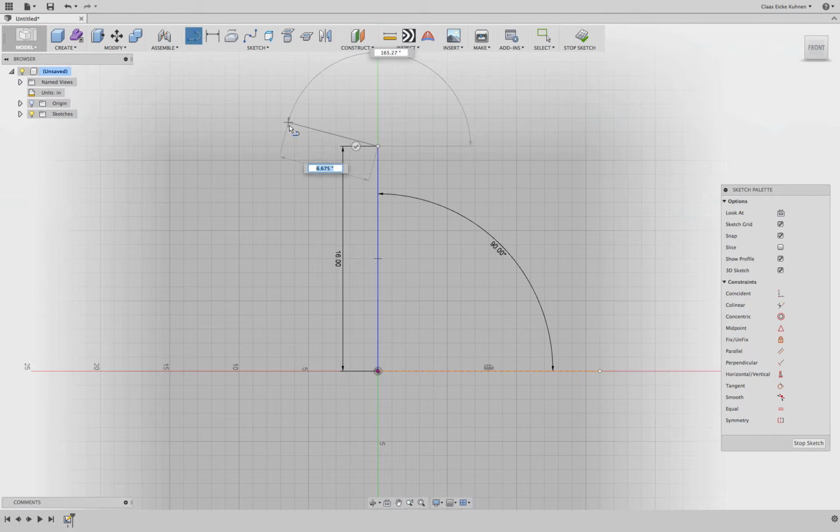Okay, then for example 4 more inches up, there I just simply use the grid. And then, for example, 9 inches to the outside, because we have an 18-inch diameter, click. And if I go down and maybe 2 inches to there, click, and to the end, click.